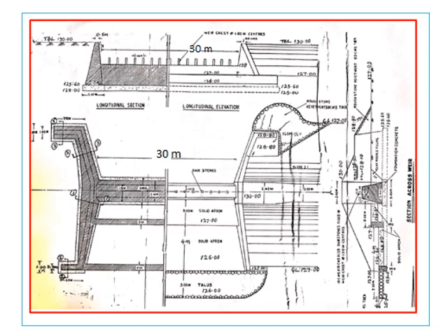Whatever you have surveyed on the site has to be reproduced onto the drawing sheet so that these drawings can be done. Also, we expect you, before doing the drawings, to design all the components required. It is not simply drawing. I didn't concentrate much on the earthwork calculations which you will be doing. It is a part of the survey work. After you do the survey work, you already have fixed the top of the bund. You already have the L sections and the cross sections, and all the levels are already done.